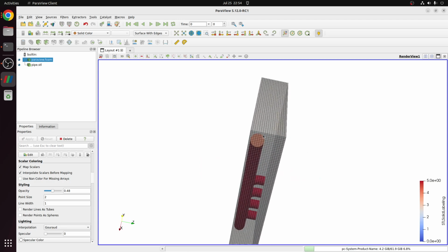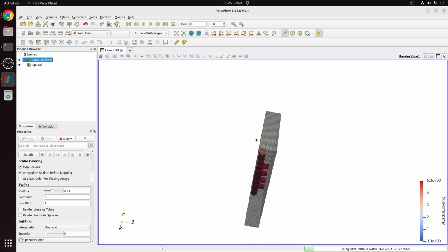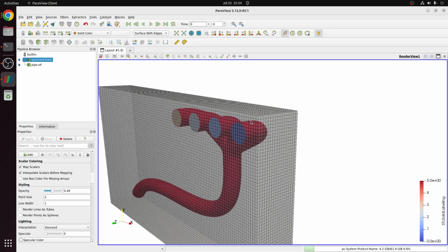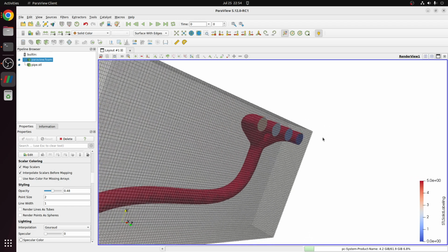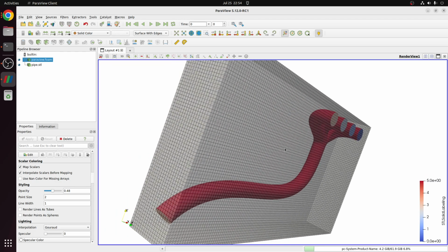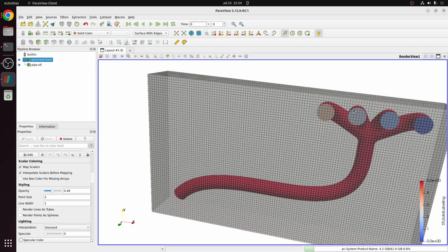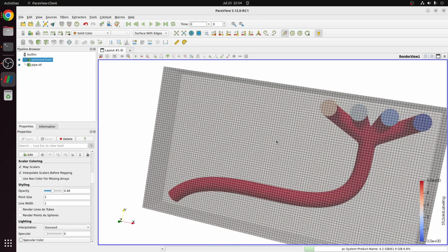You're getting my point, right? So the background mesh can be this, and what we can do is improve the refinement levels while making the snappy geometry. That is the idea. This base grid size is level 0, that you have to keep in mind. In snappy, for each surface, we will give the level that we want, so at that time you have to make sure we give more refinement while making the snappy mesh. That is the idea, Viraj.